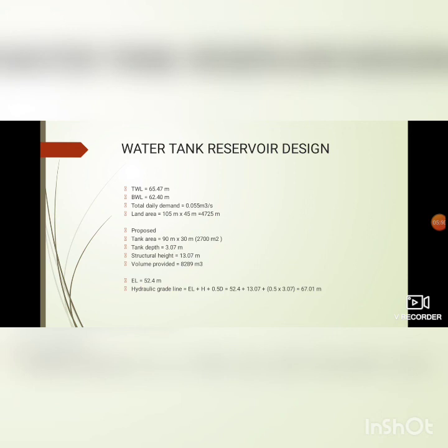Tank depth is equal to 3.70 meter, and the structural height is equal to 13.07 meter, and the volume provided is 8,289 meter cube. So the elevation level is equal to 52.4 meter. Hydraulic grade line is equal to 67.01 meter.